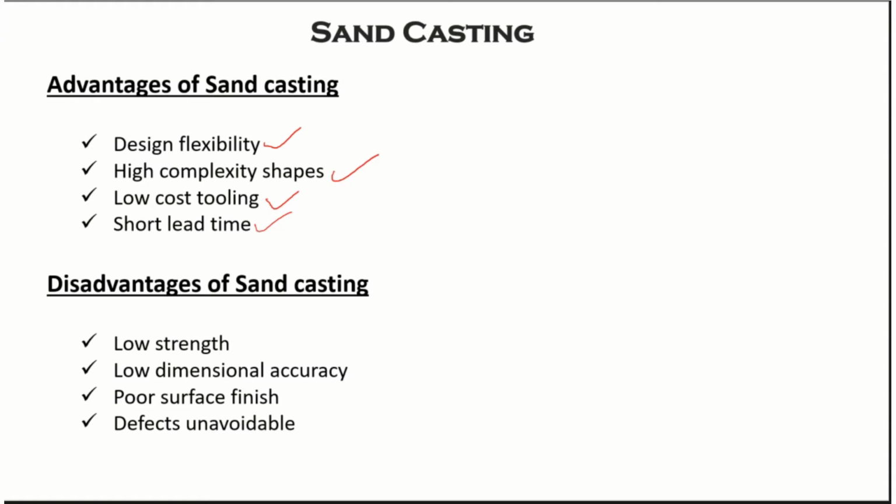However, sand casting has several disadvantages. The disadvantages are that it has low dimensional accuracy, poor surface finish, and some of the defects that are raised during sand casting are not avoidable, or the minimization of those defects cannot be controlled very easily.